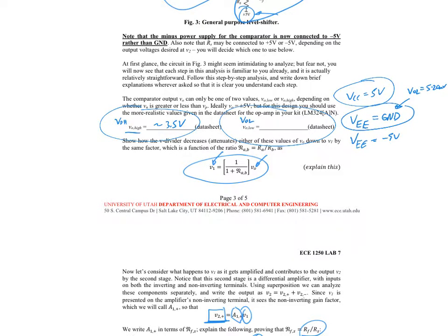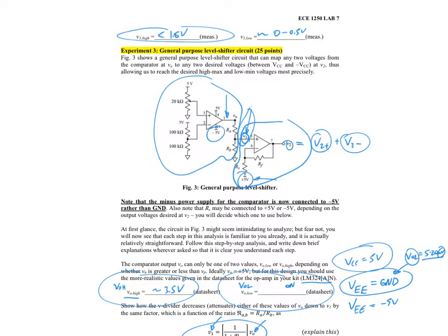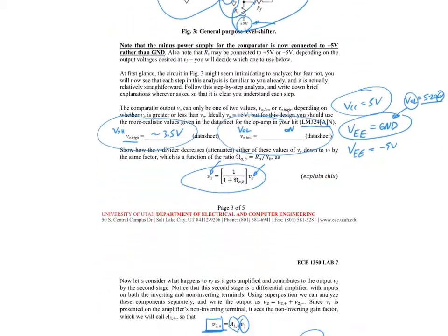And you'll see if you look up this data sheet for this guy, and I suggest using the on semiconductor data sheet. On page 3, I think, you'll see a bunch of values, and on the far right of the table, it'll give you the units. And it's in millivolts for VO low, and it'll give you VO low when it's loaded down with either, I think, a 2K, so it's suggesting that this output here has either a 2K load or a 10K load here. And we're using values that are at least 10K, so using the 10K load is going to be more accurate, more relevant to what we're doing.